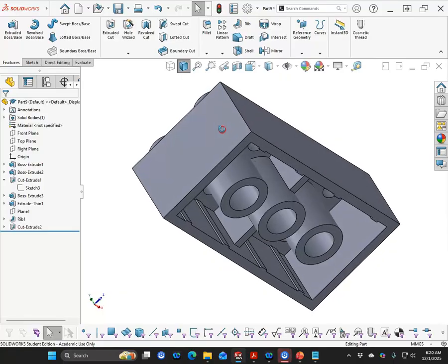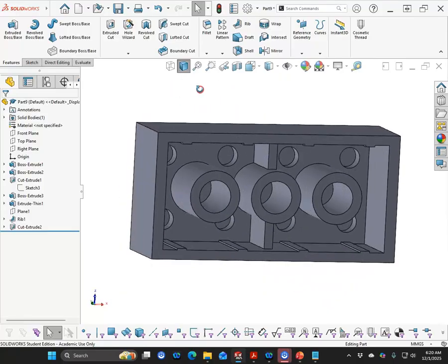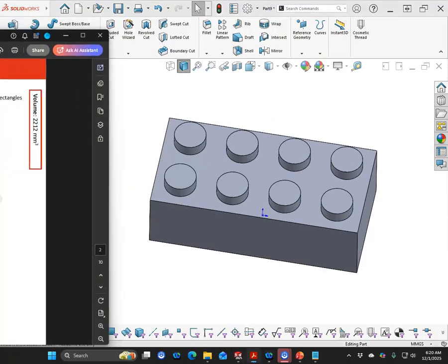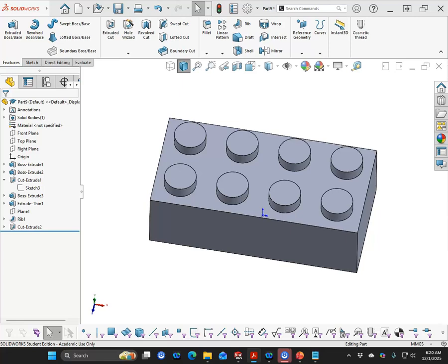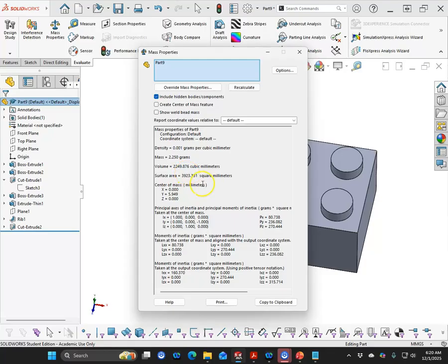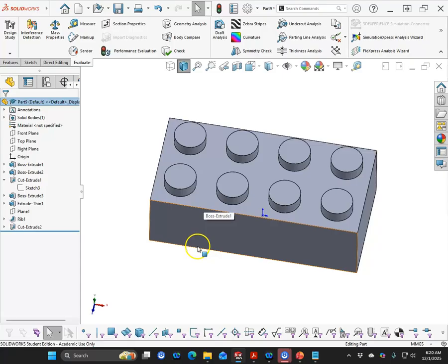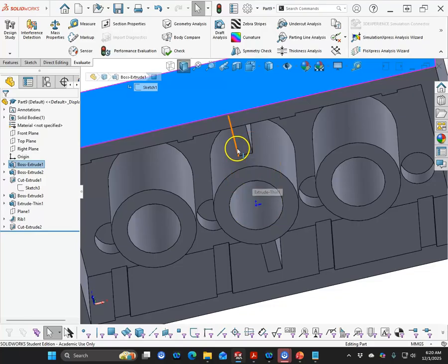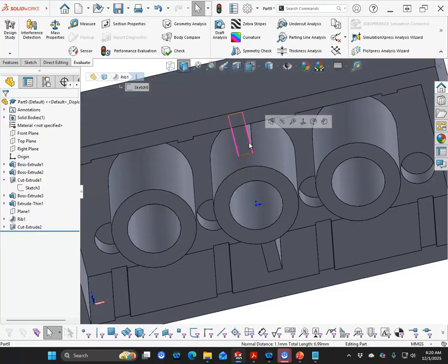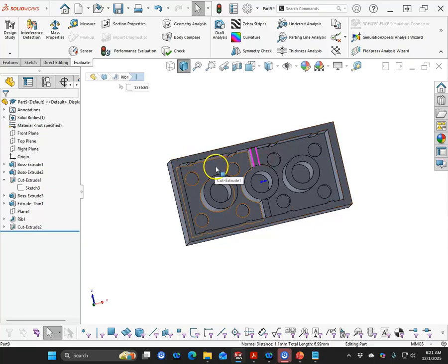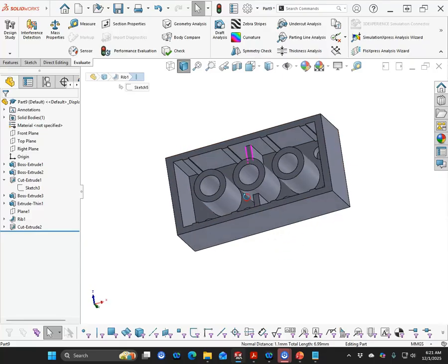One quick look. So we have a volume of 2212. Let's see how close I got. Mass properties, 2249. All right, we're close. So let's just double check a few things. Did that go both directions? Normal distance 1.1, 1.1, 2.3, 1 millimeter.